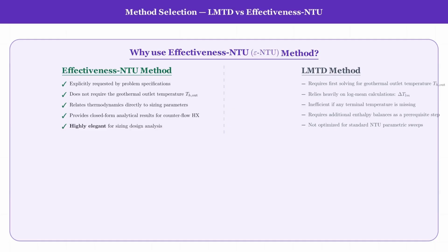Third, the effectiveness NTU framework directly connects the thermodynamics to the sizing parameters. Once the effectiveness is computed and the NTU is extracted from the analytical relation, the required surface area follows immediately. The LMTD method requires more intermediate steps to reach the same endpoint.